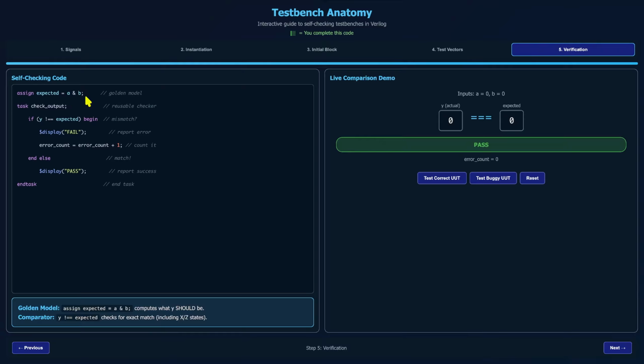But in general, there's an abstraction level where you know what the expected output would be. So you're making a comparator. You would know, with a C-like command or a MATLAB-like command, you could test whether A is bigger than B. But your circuit design actually might be logic equations that implement the comparator. And so those aren't the same thing. Logically what expected should be might be different than how you implement that with a circuit.